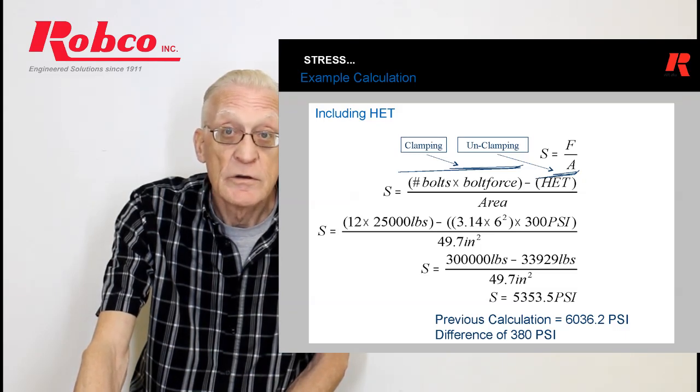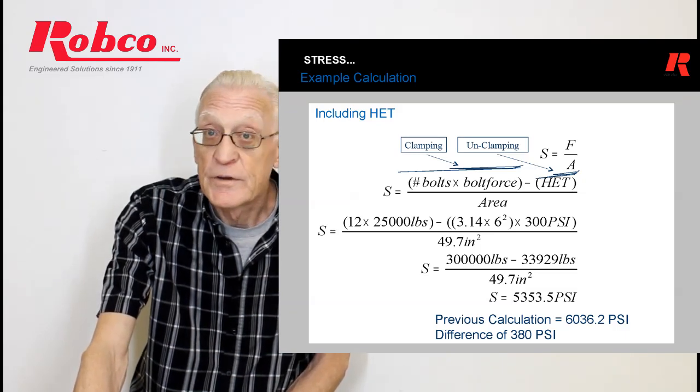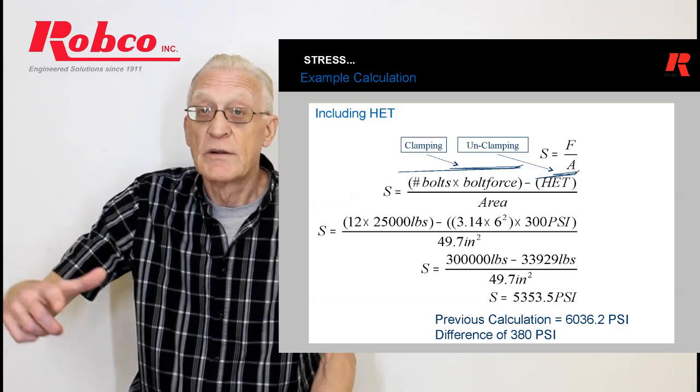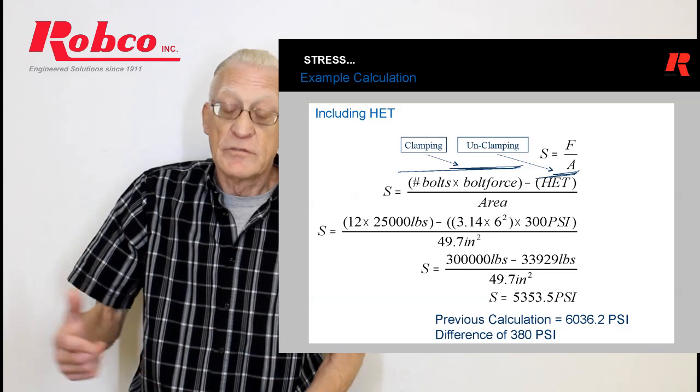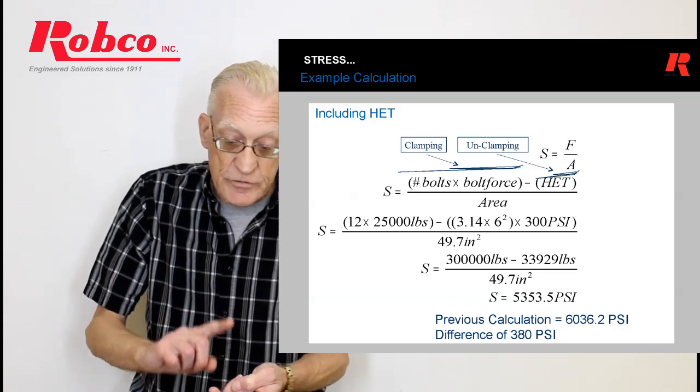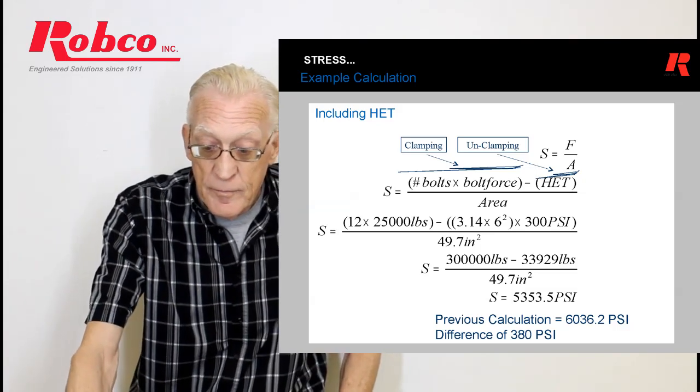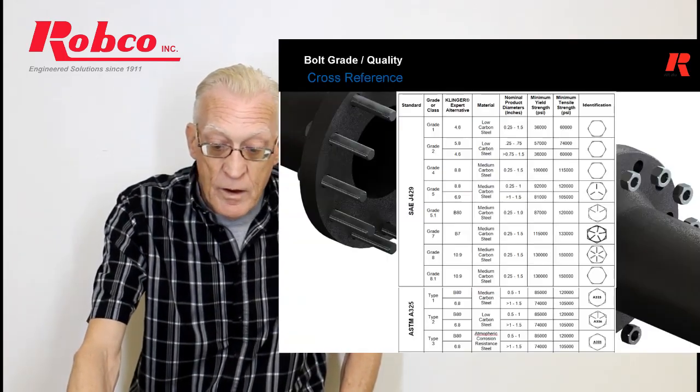You have to adjust, bring your yield from 50 to 60, put more torque on your bolts, stretching that, but then of course you have a limit. There's a limit on the compression on the gasket. There's a limit on how far you can stretch the bolts before things come apart.